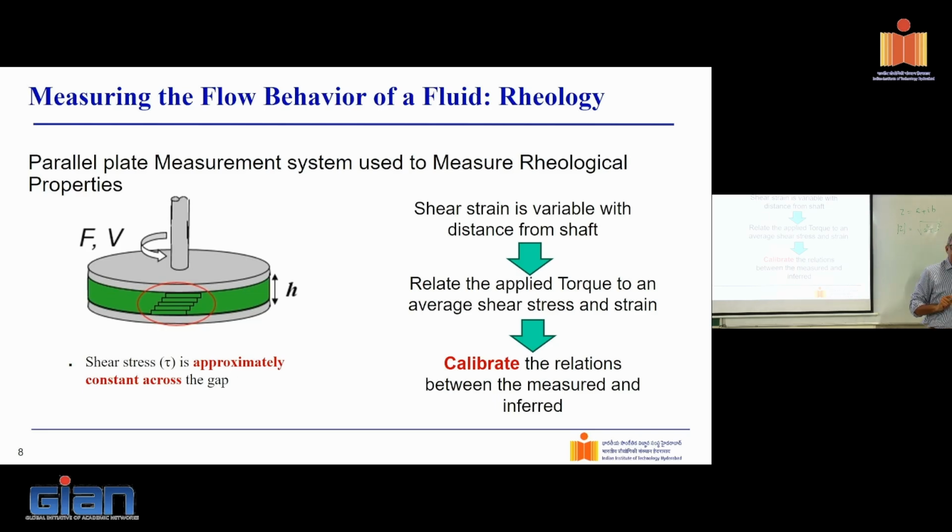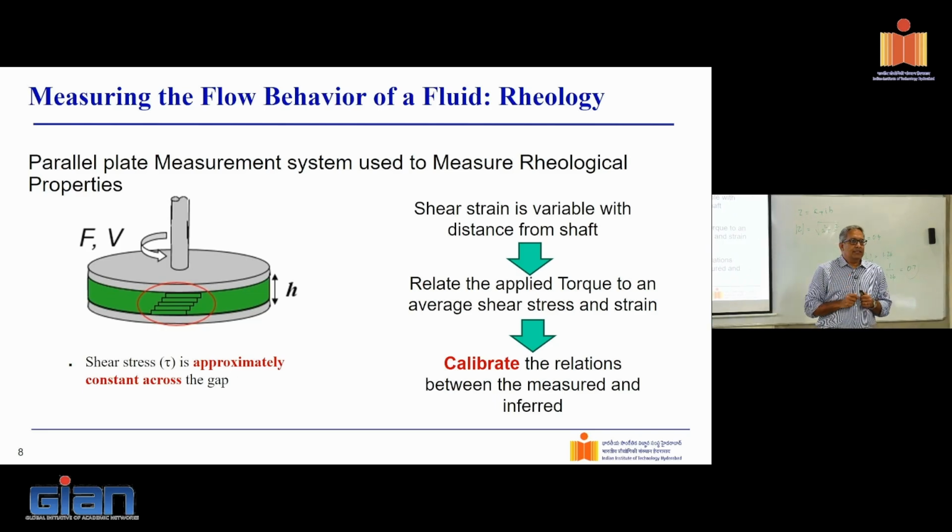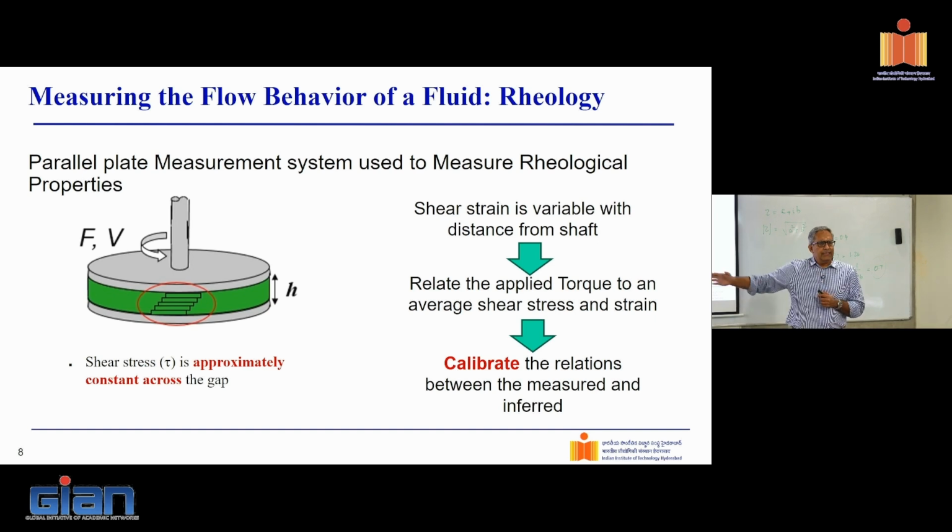Whenever you rotate something, where does the resistance come from? Torque. In this case, it's clearly coming from the liquid that is here in the gap. It's getting sheared and it's giving you the resistance. Is there any other contributor that I need to worry about? Inertia. When you spin something, even if it were air, suppose I remove this liquid and simply put air, there'll be inertia. And that will also contribute to resistance. And that resistance also increases with the rate at which I spin this thing. That is the rotational inertia.